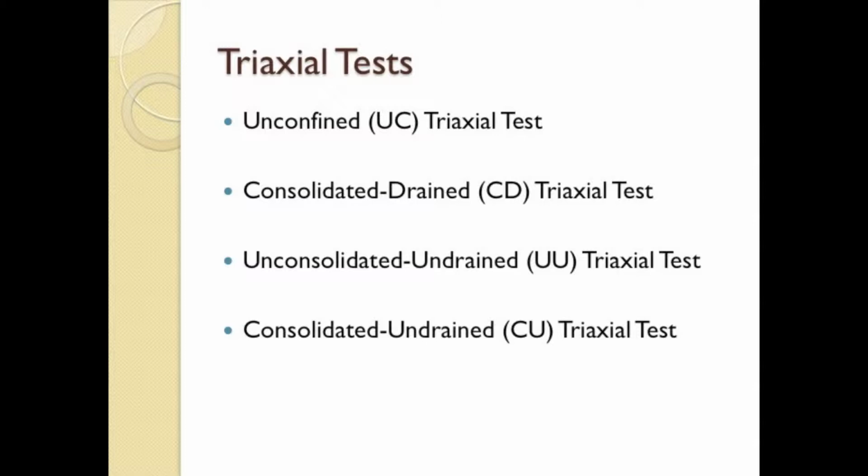Third, unconsolidated undrained triaxial test, which requires no sample consolidation and a closed drain line. The sample is not consolidated by the confining pressures, but rather left as is. The closed drain line allows pore pressures to build as the sample is compressed.